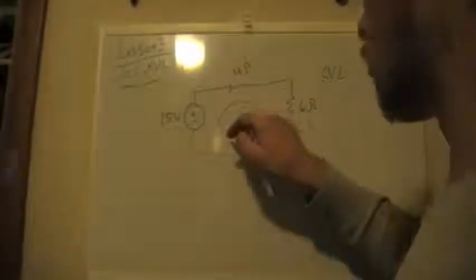So this is what I mean. If we have a certain amount of current that's sourced by a supply, that current travels through every element of the loop because the charge only has one place that it can go. So elements that are in series with each other have the same current going through them. But say we added another loop over here, now there's 2 loops, so there's going to be 2 different currents because the current is going to split at this node right here. And you're going to get an I2 and an I1, and then they'll recombine down here back into I total. So this is a very important concept: current splits when it goes into different loops, but the current going through a continuous loop like this is the same. So the same current goes through both the 4 and the 6 ohm resistor.